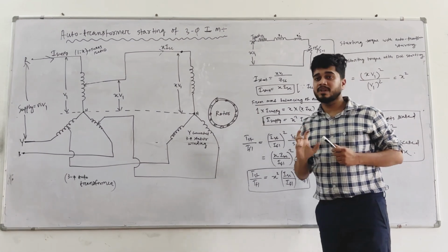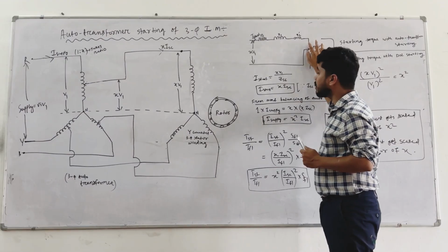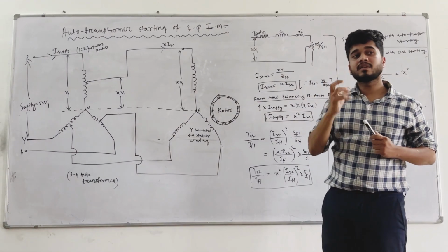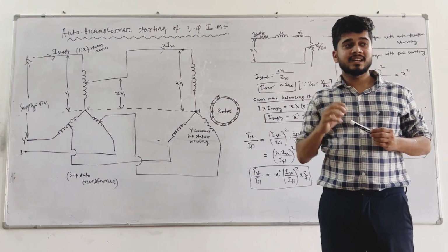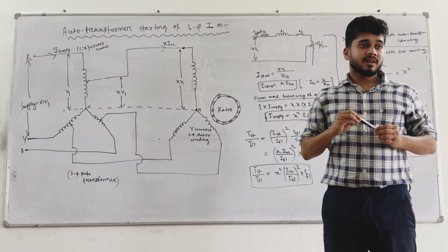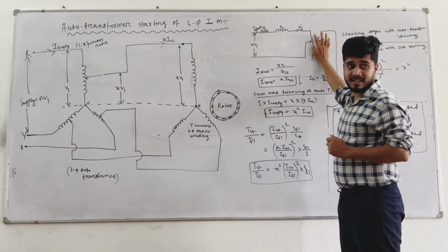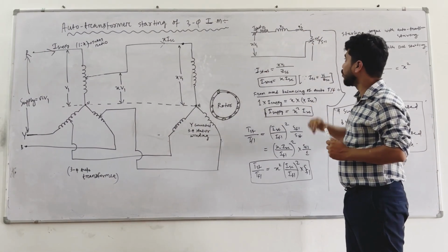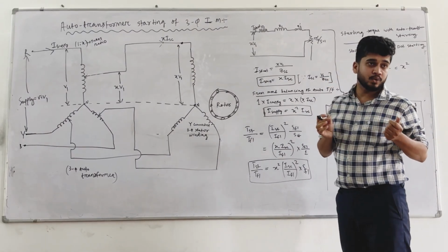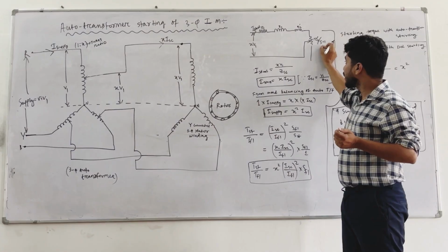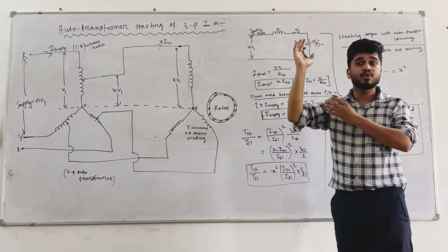Now tell me, if slip is 1, is the resistance of the rotor minimum or high? High. So you are saying that if S is equal to 1, the resistance is high. No. I have already told you, when slip becomes 0.1 or 0.2 and you divide R2 dash by S, that value is going to increase.